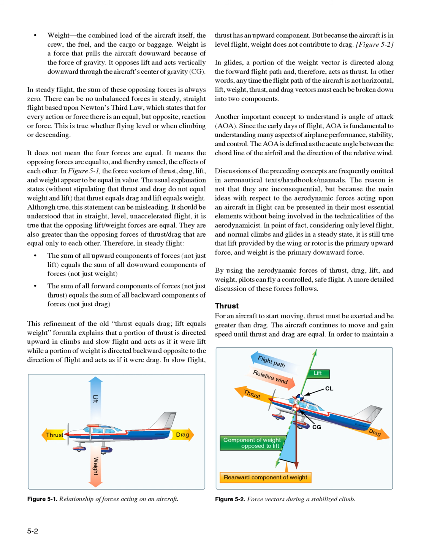Another important concept to understand is angle of attack, AOA. Since the early days of flight, AOA has been fundamental to understanding many aspects of airplane performance, stability, and control. The AOA is defined as the acute angle between the chord line of the airfoil and the direction of the relative wind. Discussions of the preceding concepts are frequently omitted in aeronautical